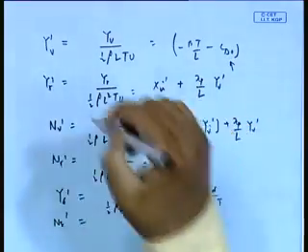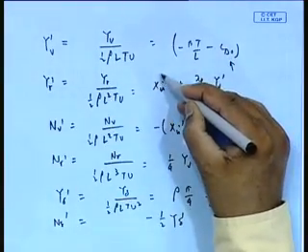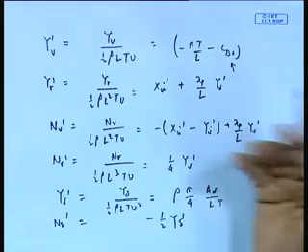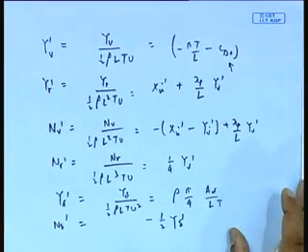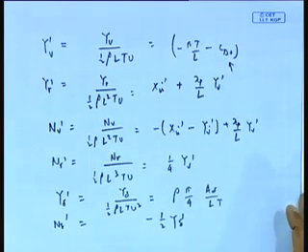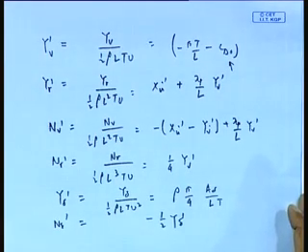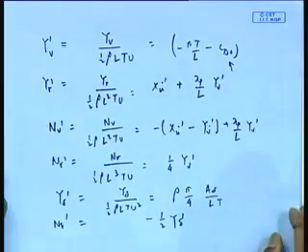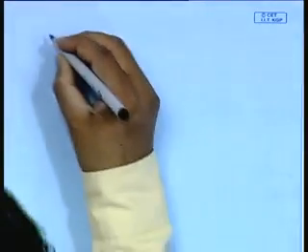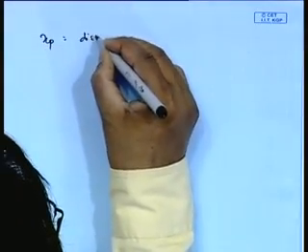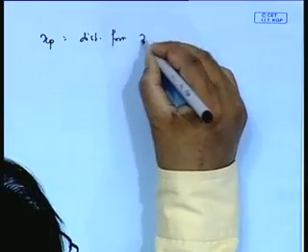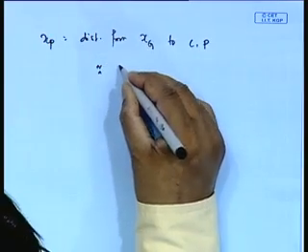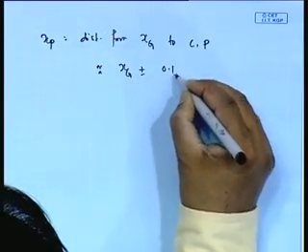Yr dash. Another thing in this set of formulas is that they use something called added mass term corrections. To that, this term comes into the picture here. Again it comes from theory. Now here this Xp is what is known as the center of pressure point, and normally Xp is the distance between the center of gravity and center of pressure, and this Xp is approximately, let me write it down so that there is no ambiguity, xg plus minus 0.1 L.